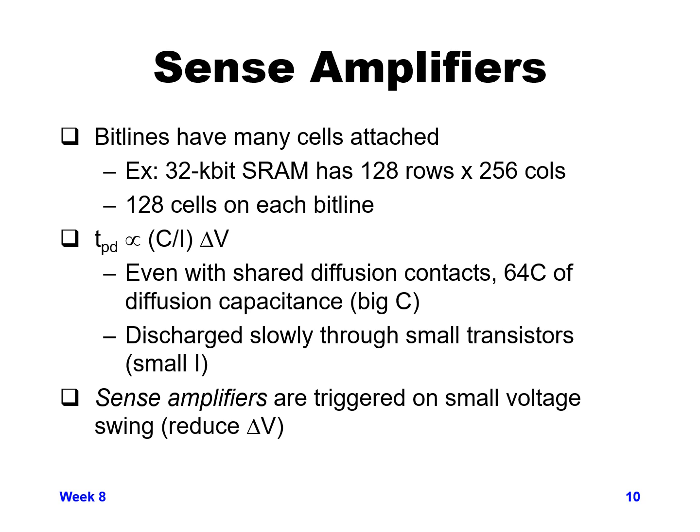Several slides ago I showed just having an inverter to read out the value. In general, for most SRAM designs, we don't have an inverter there, because that would mean we'd have to go past a 50% point in order to flip the inverter, and we don't have the time, or don't want to take the time, to get to a 50% point.